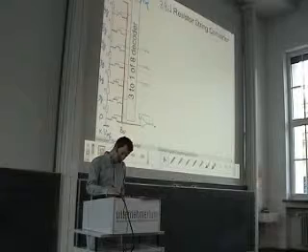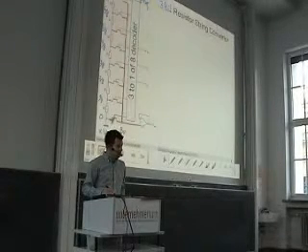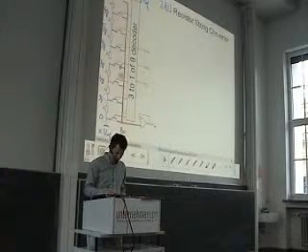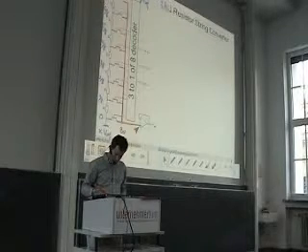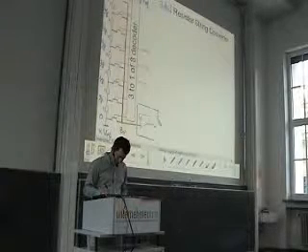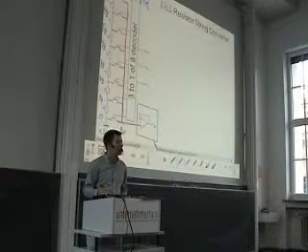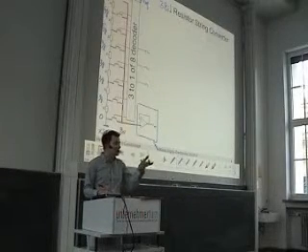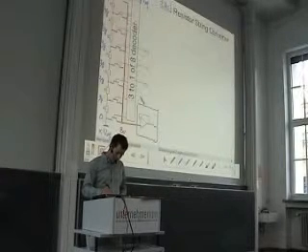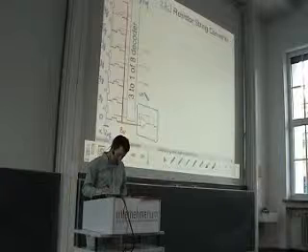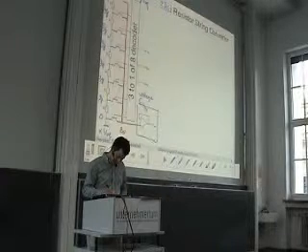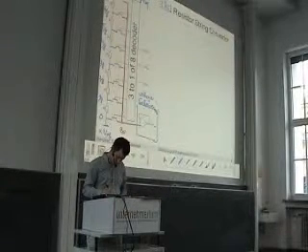Then we may enable any of these switches. So the respective voltage is connected to the voltage bus, and this signal is then fed to an operational amplifier which is configured as a voltage follower. And this is very important because this exactly assures the requirement that no current is drawn out of the resistive voltage divider, out of the resistor string. So we have here a voltage follower as buffer. This is a buffer.